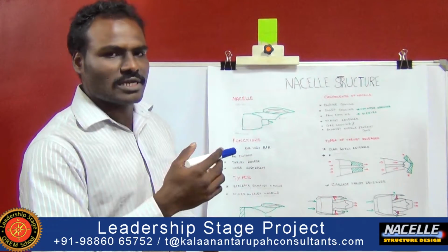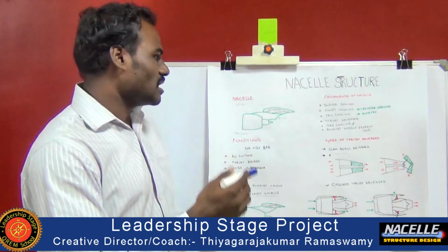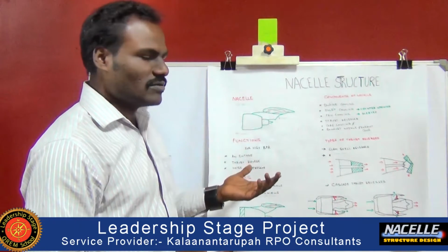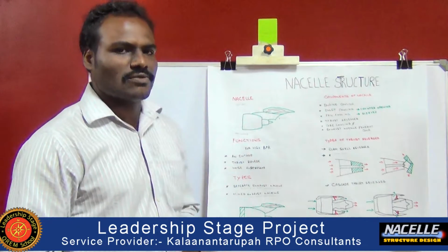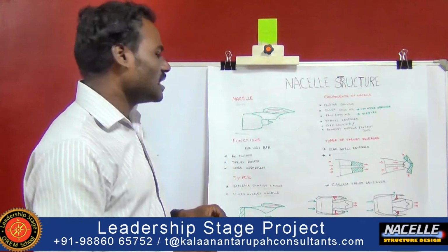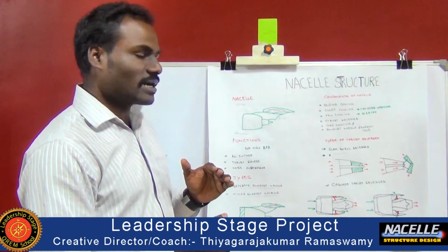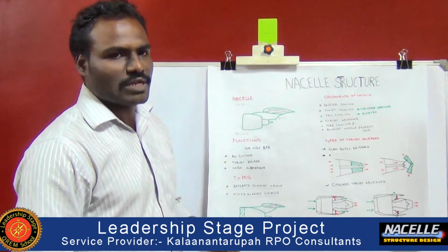The rest, about 60% of the air which is sucked in, is propelled outside, which helps in the thrust reversing process as well. So, in order to increase the efficiency of a nacelle, we design it with specific design criteria and higher bypass ratio values.